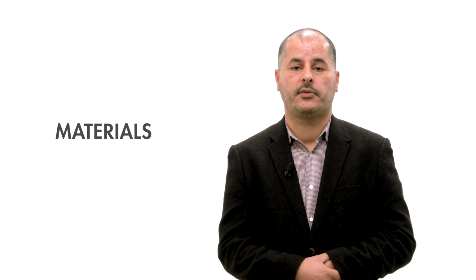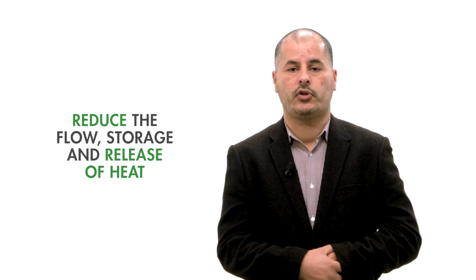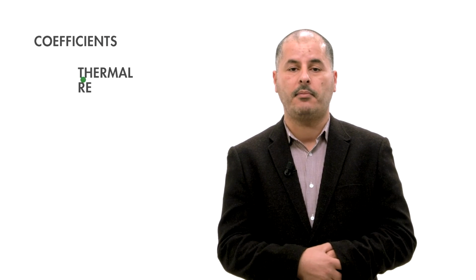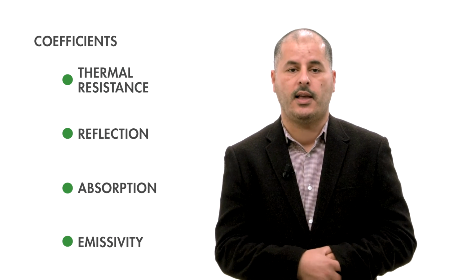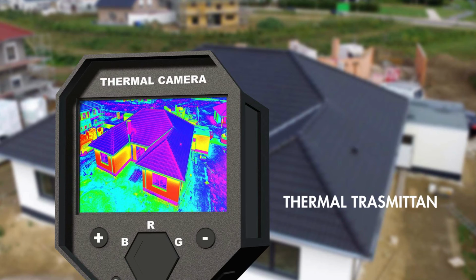Finally, we can mention materials for a climate-responsive strategy. The properties of material are important. It can reduce the flow, storage, and release of heat in warm, hot climates. The thermal resistance, reflection, absorption, and emissivity coefficients are important factors to reduce the energy demand for cooling. Their thermal transmittance U value has a major influence on the cooling demand.